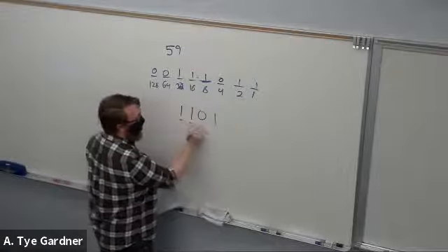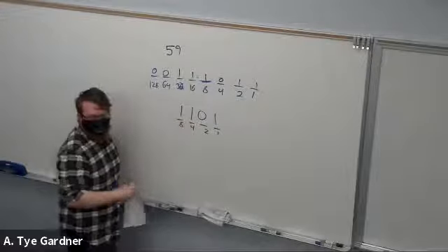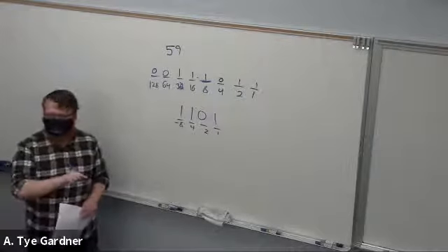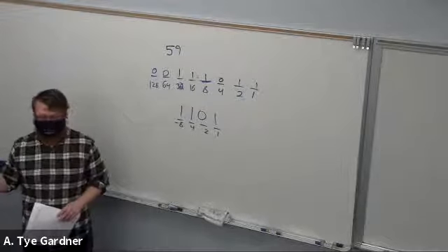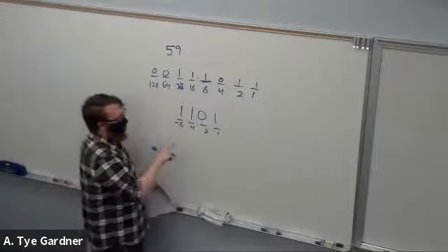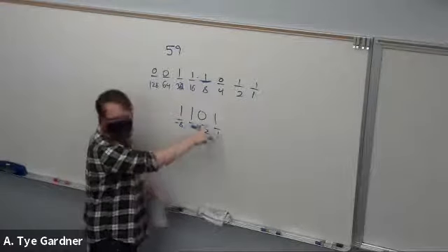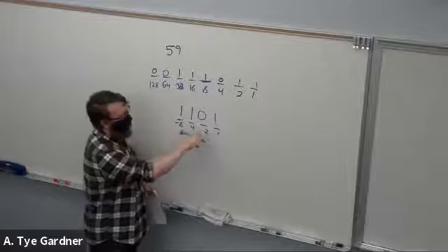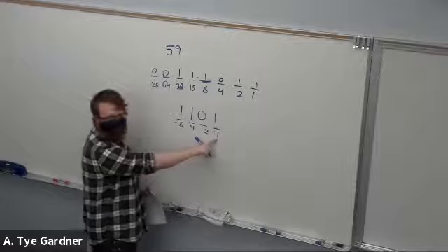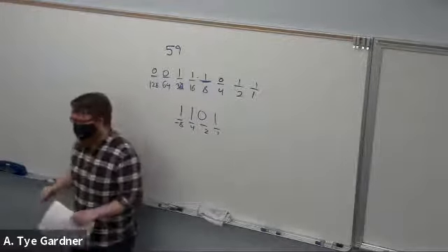So here, where we have 1, 2, 4, 8, the biggest bit is -8, which is different than signed and unsigned. If I just ask what this is as a signed number, it's -101, as opposed to 2's complement, which is -8 plus 4 plus 1. Keep those straight, because something like that could show up.